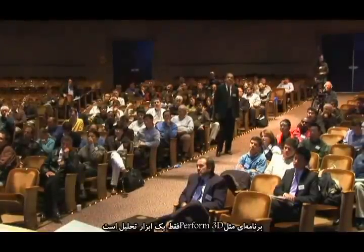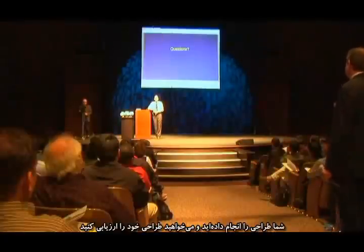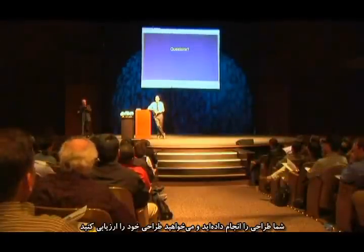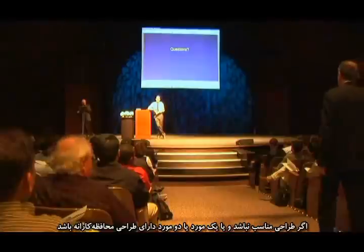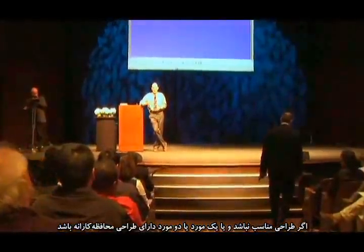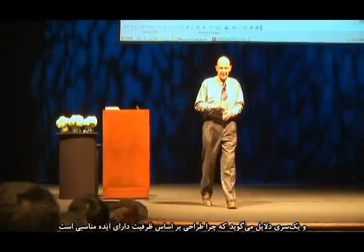A computer program like Perform 3D is just an analysis tool. It assumes that you have created your design and you want to assess the performance of that design. If your design is not okay, if it's either unconservative or maybe too conservative, it doesn't really give you any guidance on how you should change it. That's up to you as the engineer. And I would come back to the reasons why capacity design is a good idea.